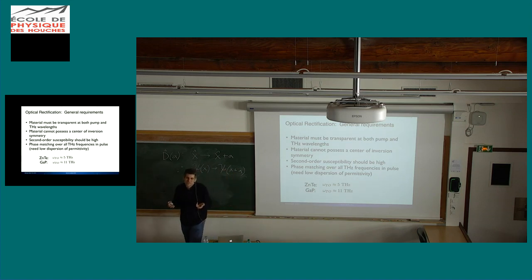that's actually fairly strong. And so that's the problem, those optical phonons tend to land in the terahertz range somewhere. And so obviously you have a problem with the absorption, the transparency, and also you get a lot of dispersion when you get close to that wavelength. So that's why you sometimes use these different crystals. Gallium phosphide is somewhat lower efficiency, but it has a higher frequency optical mode. So it's often used, especially for detection purposes.